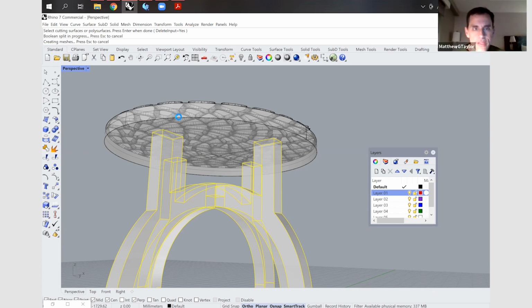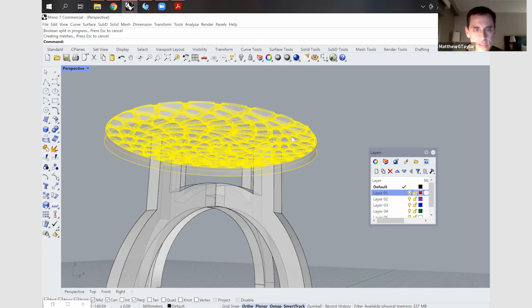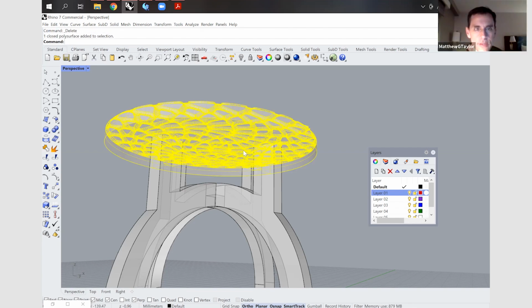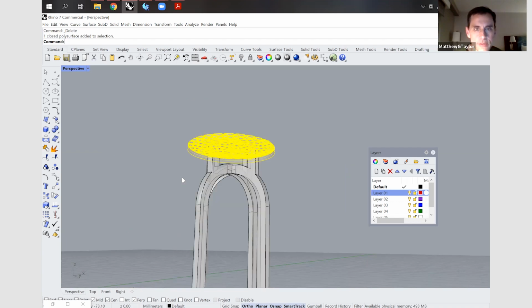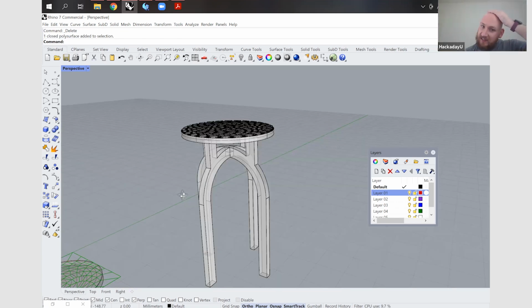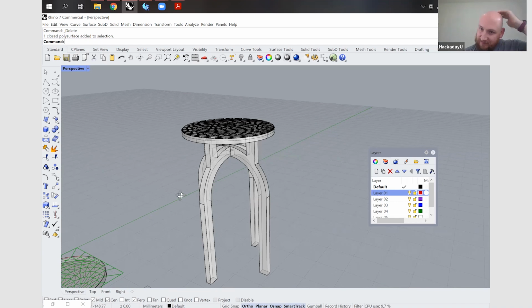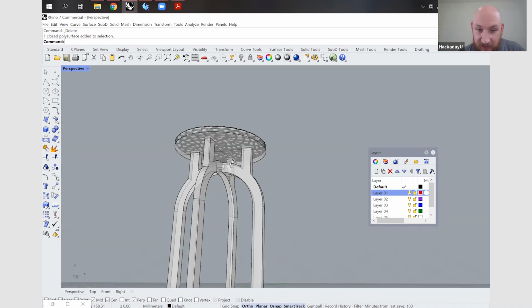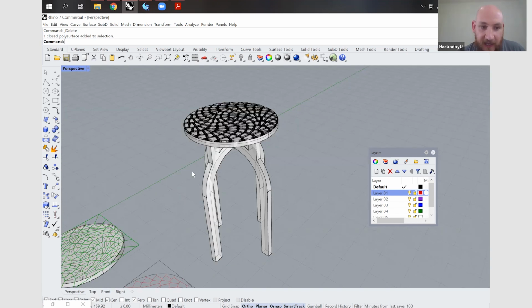James, do you do everything line to line for your CNC work, or do you leave a little bit of gap, a little bit of tolerance or clearance in those? I'd leave a little bit of clearance. How much would you leave? Depends. I usually like a millimeter. Oh, do you mean vertically a millimeter? Definitely not on the other side.